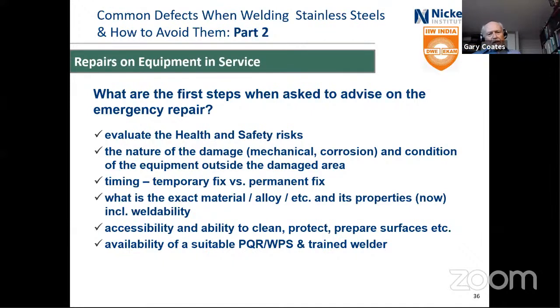So the accessibility and ability to clean, protect, and prepare surfaces. I mean, if you have a stainless steel that's covered in corrosion product with product from the process, and the welder can only get in there with a wire brush to clean it, he's not going to do a good job. And some alloys are very sensitive to the cleaning procedures. 304L, 316, important to clean, but if they're not 100% perfect, well, you can do a pretty good job with them. 6 Moly and duplex, you really want them super clean.